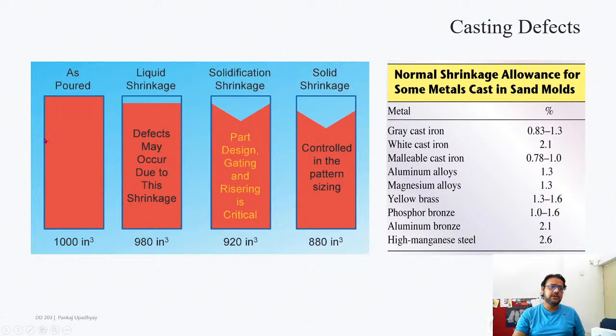The reason this kind of shrinkage pattern happens is that when the outer layer is shrinking, it pulls in material from the other side so that it does not change in dimension, and because of that the material will reduce from the center, and hence you will get this kind of a shape.